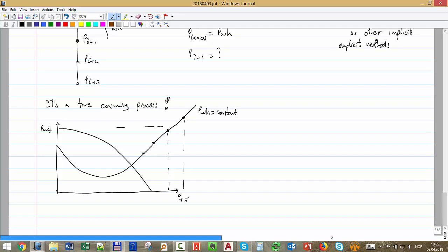And for each one of these points, you had to make that integration process. You had to go from wellhead all the way to bottom hole to calculate the flow pattern in each one of them, calculate delta P until you reach here, and that's the point you're plotting here. That's extremely important. Each one of these points takes a lot of effort to calculate. So why does the curve look like that? Here it is very clear, right?